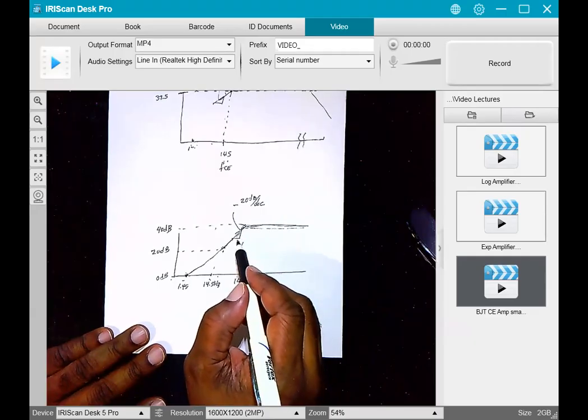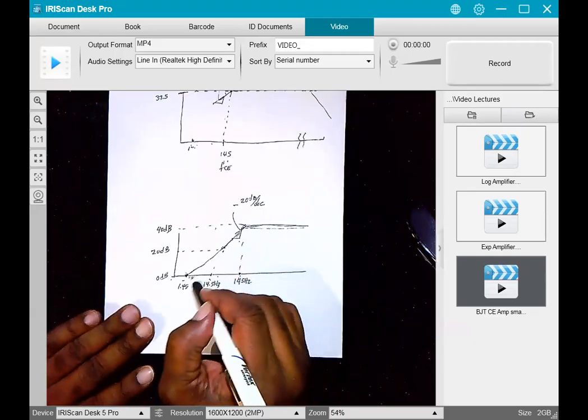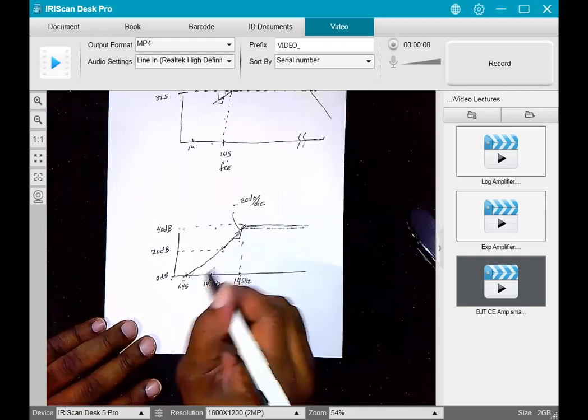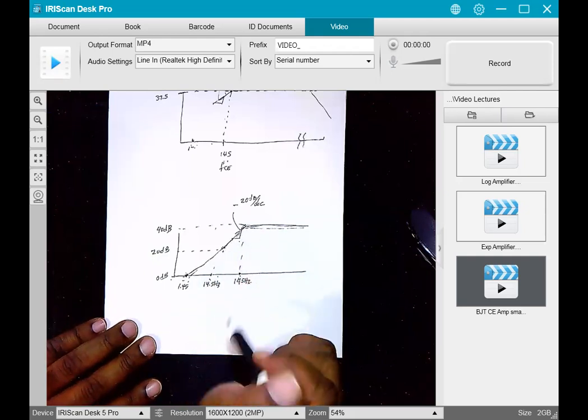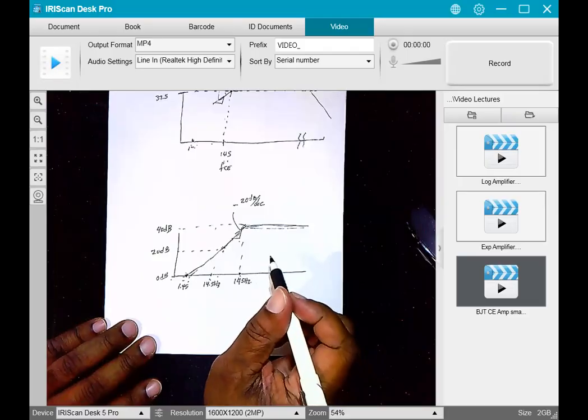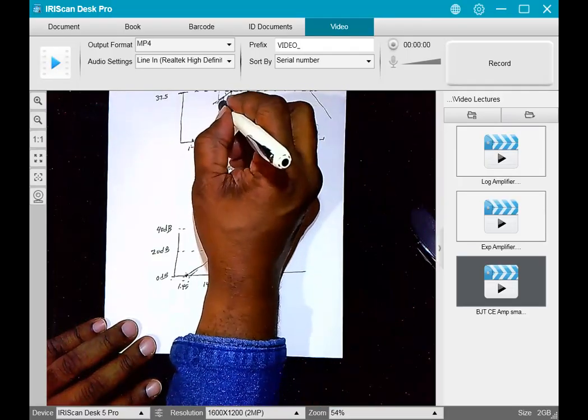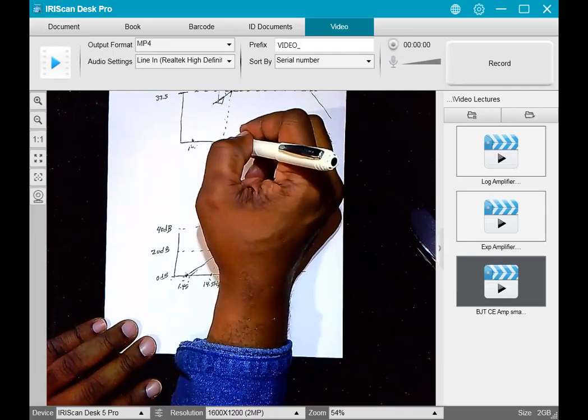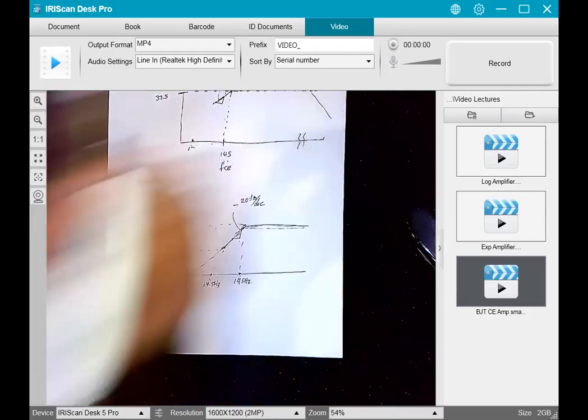Normally this is called a Bode plot, and when I was a student, this was covered heavily in AC circuits. So we did a lot of this long before we ever got to electronics. So over here, we had 20 dB per decade slope for this first pole, which is F sub C.